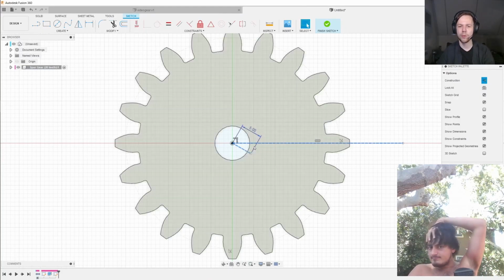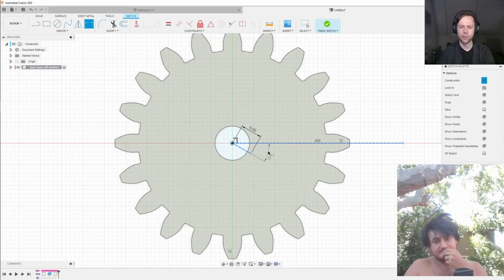And then I want to specify the angle between this horizontal line and this new line that I drew here. So I select them both and press D. And then the angle that I want...